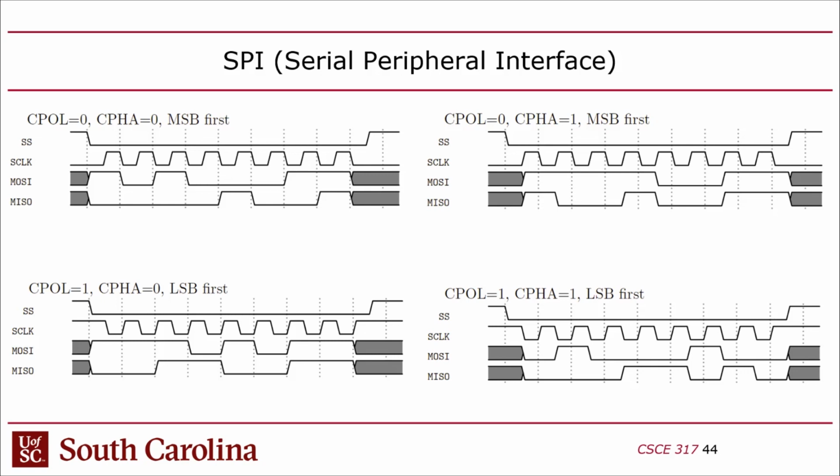Yeah. My dissertation was actually about looking at a lot of those eye diagrams, where you take bits of a channel and keep superimposing them, like on an oscilloscope. You can see the clock edges are really soft, and not only that, they also have jitter in them. They're moving around. So what you end up with is an eye diagram, exactly what you're talking about. The eye closes the more jitter you have.